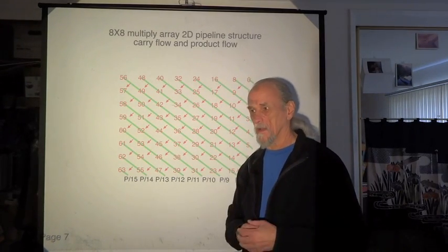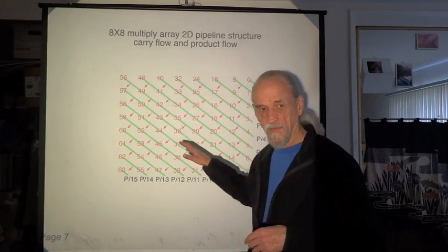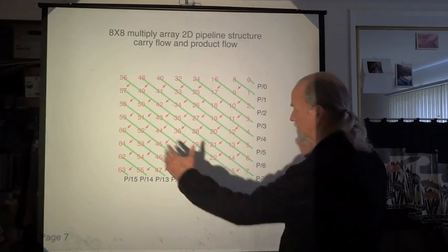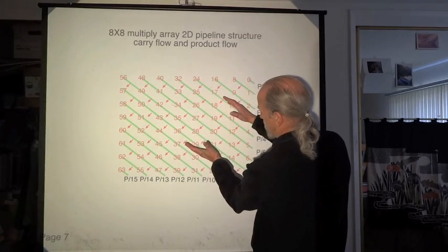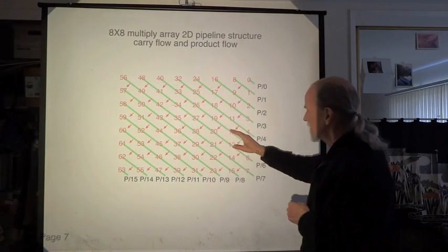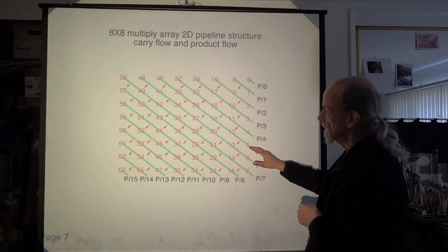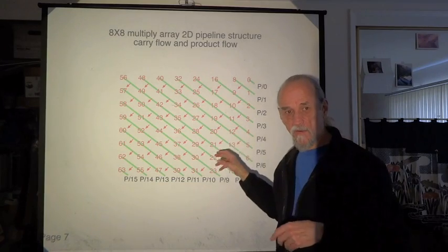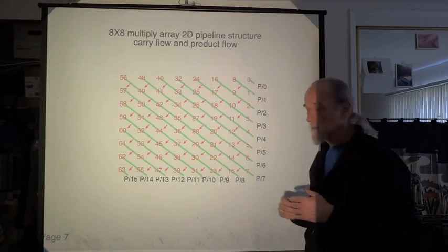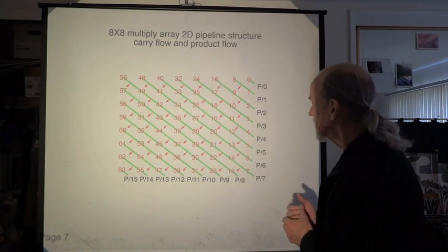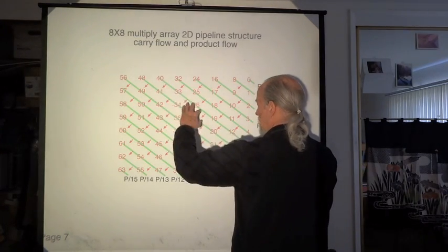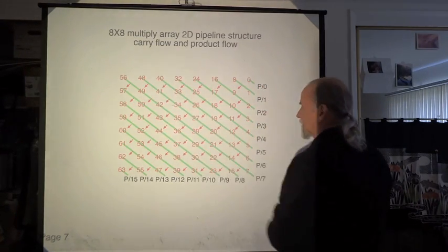So these diagonals now correspond to the adder columns in the array, right? So when we squeeze the array down, the adder columns got diagonalized, and the incidence of simultaneous partial products correspond to the partial products that we want to add together to get a product output. Okay, so now all of these happen simultaneously, 40, 33, 12.